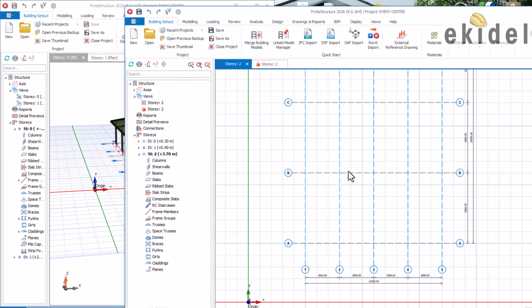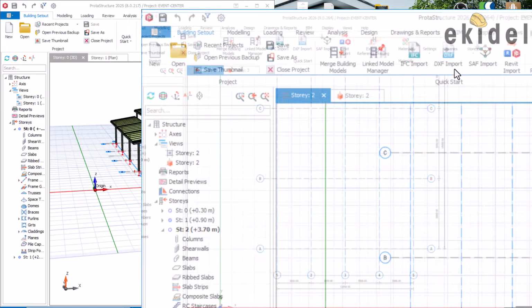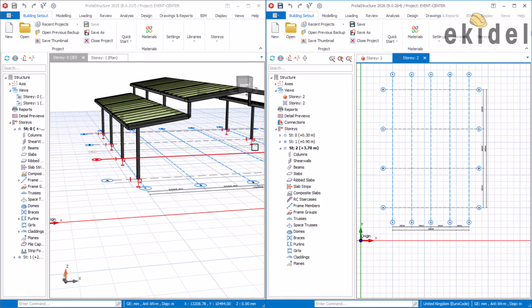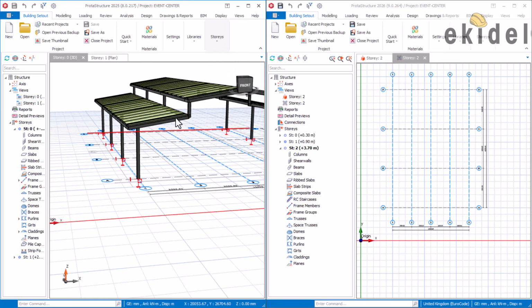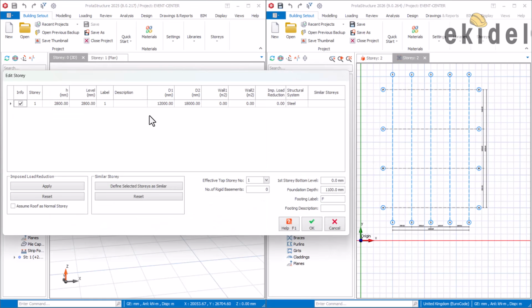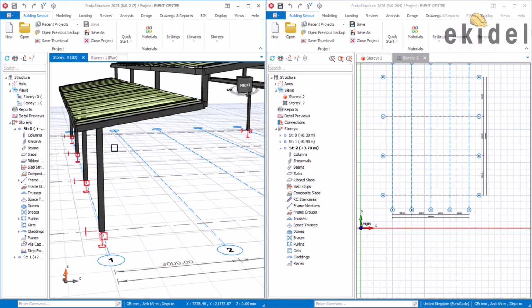Now on this place now, we are on story 2. I will have to move this backward again. Let me do this something like this. Something like this. Come here and keep. So now that we are back here, let's confirm the story height of this particular one that we used here. So we'll come here, edit story, and then confirm the exact story height that we use for this particular model, which is 2.8. Yeah, so you can see that here, 2.8. So 2.8 is the story height, so that is confirmed. We then click on escape, and that's also what we used here too, 2.8, when we are doing that. Okay, that's fine. So on that note, now let's insert this T column.